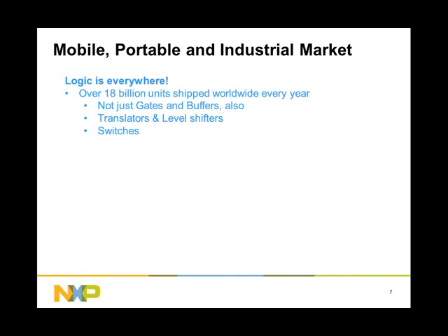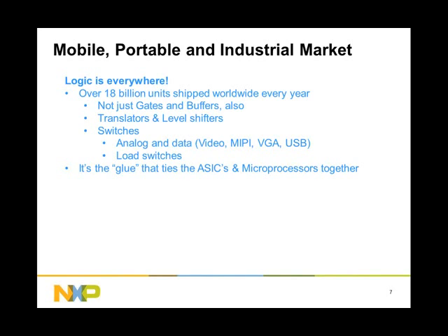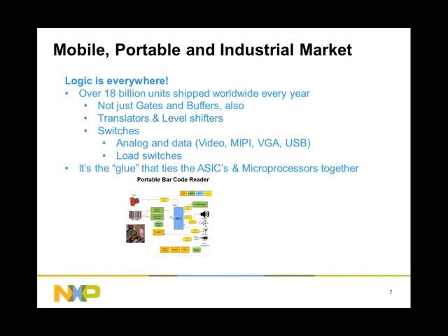Switches, and not the ordinary analog switches, but also the data, video, MIPI, VGA, and USB switches. Also, load switches. In the past, the switches that were offered from the logic groups were typically in the 5 to 10 ohm range. Now they're in the sub 1 ohm range, and for load switches, they're in the milliohm RDS(on) range. Okay. Logic is the glue that ties the ASIC and the microprocessor together.